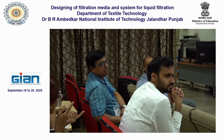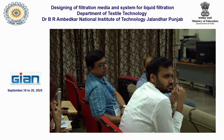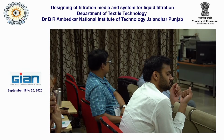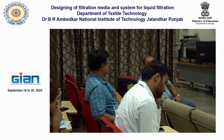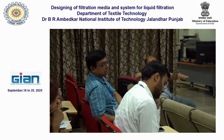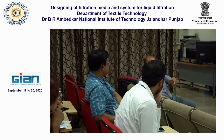But polymeric media, if we are manufacturing by electrospinning nano, can we say that is a membrane? Then you can also talk about it as textile media, because it all depends on how it is made. In some cases, to make a membrane, people make a simple sheet without making fiber. They punch holes, and then they expand it, as in geogrid and some geotextile applications. They punch the hole, and then it is expanded in both directions, so that you can produce the holes.